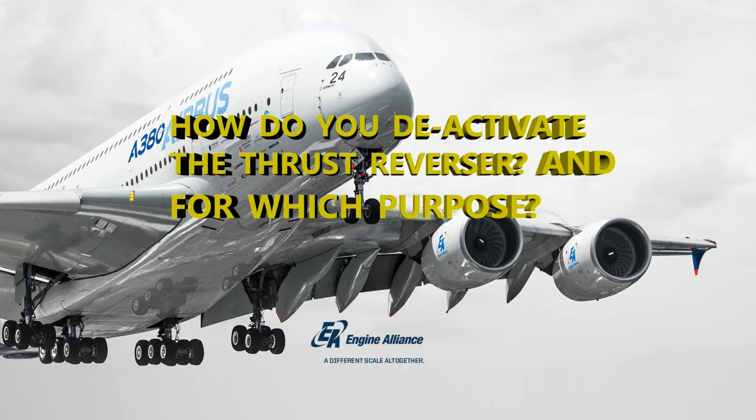All right. There's also deactivating the thrust reverser for dispatch, and with the electrical deactivation, you're still going to use the OMS, your onboard maintenance system, excuse me, and that same aspect of it, your power distribution part, because again, you're trying to shut down its source of power, which is electrical. So you're going to still be doing it that way.